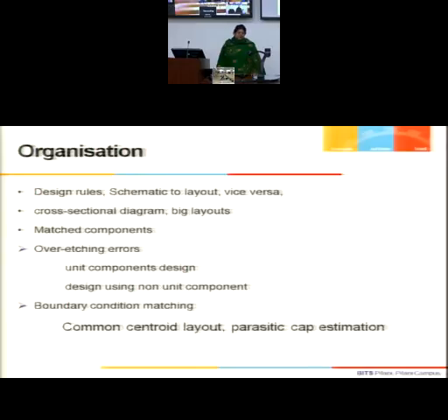How to have control on the ratio of the matched devices or the dimensions. How to have a matching of nearly 100% by matching the boundary conditions. And how to lessen the parasitic capacitance, because at the drain junction I do not want a very high parasitic capacitance. So all these 3 issues are addressed at the layout level.